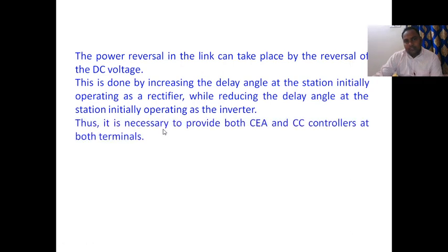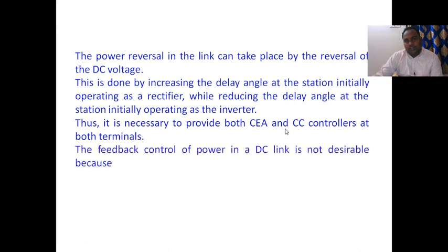Thus, it is necessary to provide both CEA and CC controllers at both terminals. What is CEA? CEA is constant extinction angle control. CC is constant current control. Both controls are needed at both ends, the rectifier end and also the inverter end.